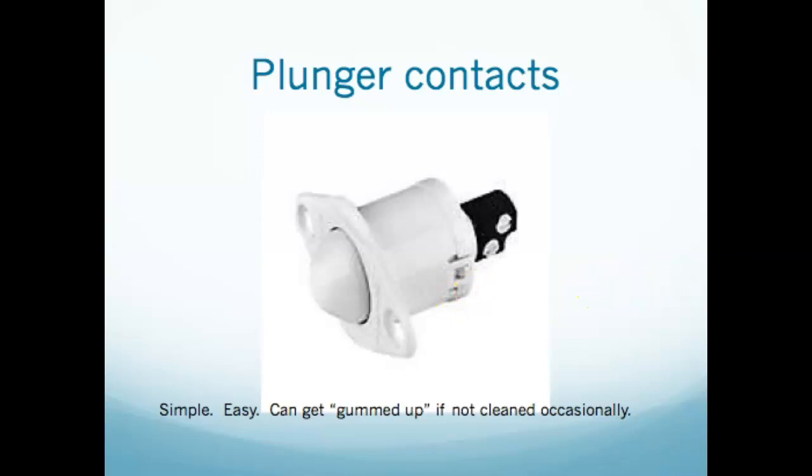It's really a plunger switch. In fact, the light on your refrigerator normally, when you open up the door, you'll see a little plunger somewhere. It's the same principle as the light in your refrigerator, really. Cheap, can be used a fair amount, needs to be cleaned, but if you used them on a door that was constantly slamming, your refrigerator door doesn't slam like a regular door does, these would probably get broken pretty quick, but they do have their use, and again, extremely cheap.